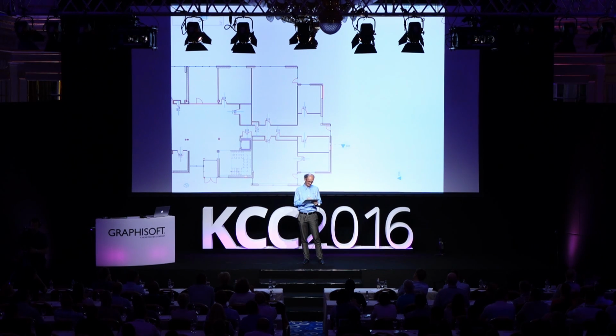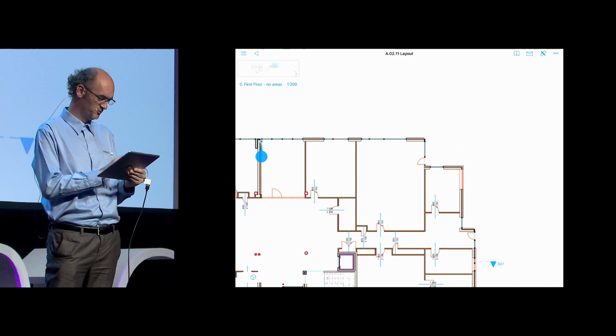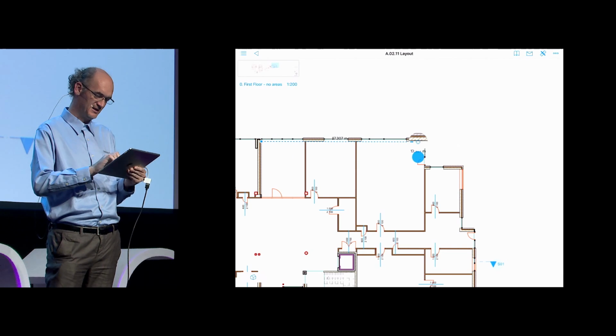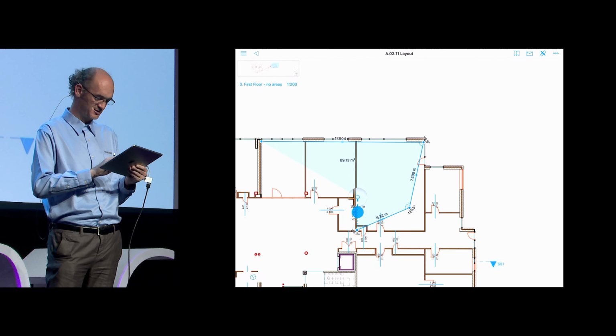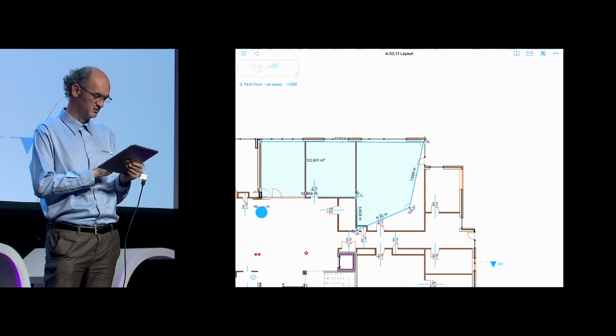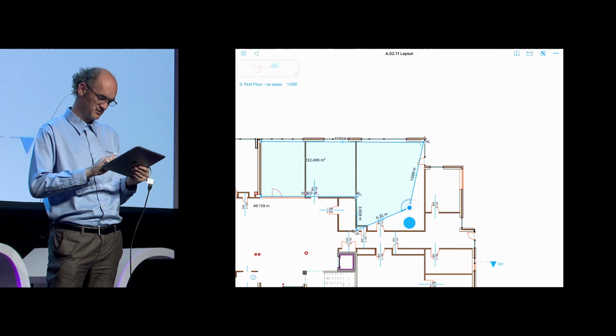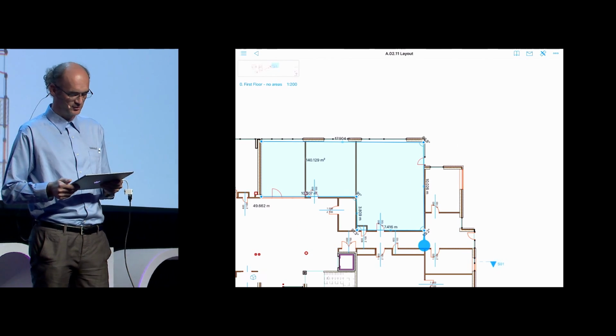I guess you mean BIMx by clapping. Okay, so measuring tool, top right corner, I tap it, I get a nice cursor. I can position it to the corners of the room. I also get a small magnifying glass showing me the exact location. And I also get the, oops, a mistake there, but don't worry. So I also get the numbers live feedback on the screen, the side, the edge length, and also the combined surface. So this is it. Last corner, 140 square meters.